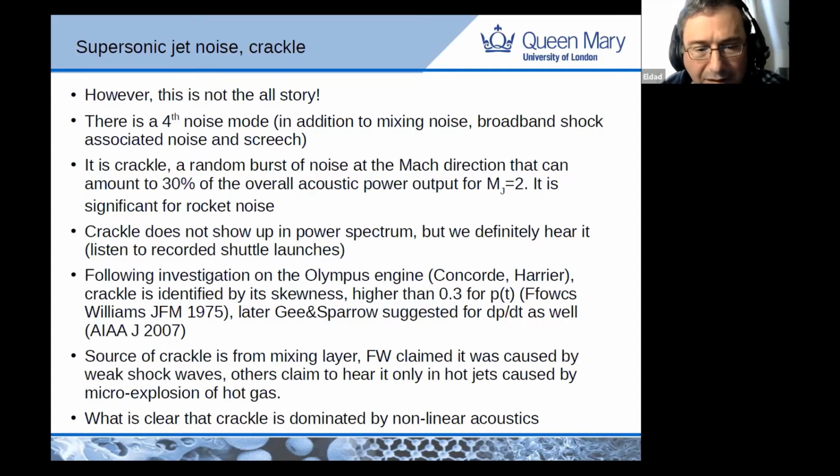Now, there's been some question about where crackle is coming from. We know it's coming from the mixing region. Ffowcs Williams claimed it came from weak shock waves. Others claim it's only in hot jets, what they call micro explosions of hot gas. What we think is that crackle is also nonlinear acoustic dominated.